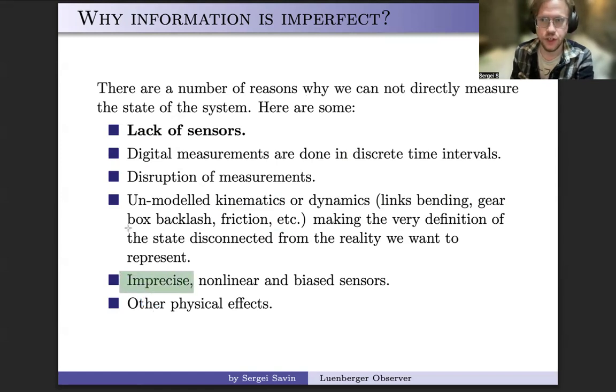So a lot of cheaper sensors or simpler sensors would not be precise. For example, pressure sensors, those very simple, very small ones, can be relatively imprecise. And the reason isn't that you cannot buy expensive sensors, but because you don't want to install very big, reliable sensors and you want something cheaper and smaller, sometimes. Some sensors, such as the LiDAR or GPS sensors, are just naturally imprecise.